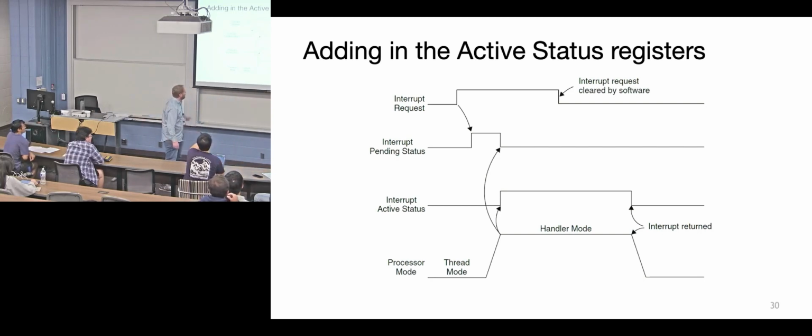It takes time, so this is indicating you have to do stacking. That takes multiple stores. You have to take your first four registers plus R12, your PC, your link register, your stack pointer, probably something else, and stick it on your stack. So that takes some time.